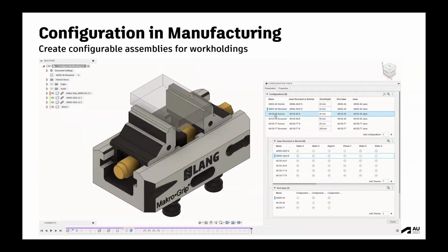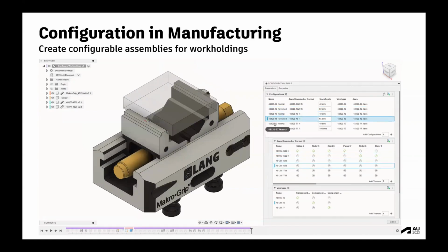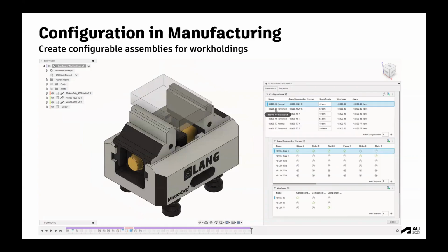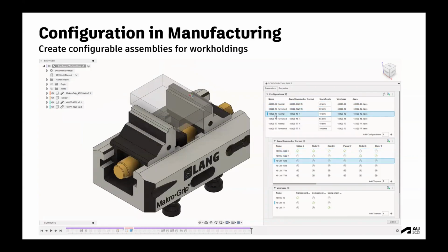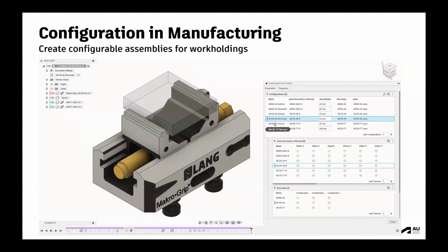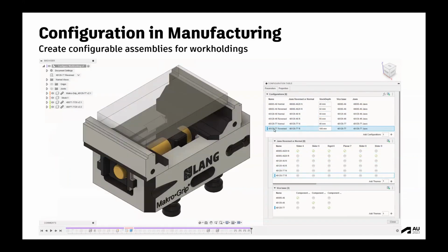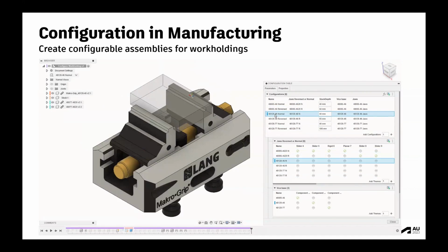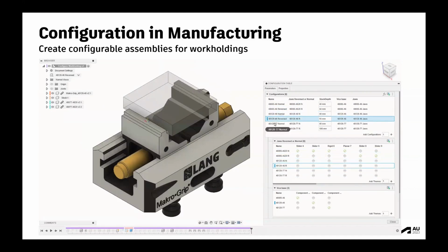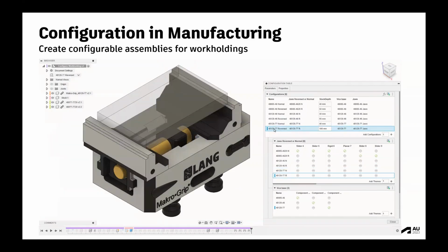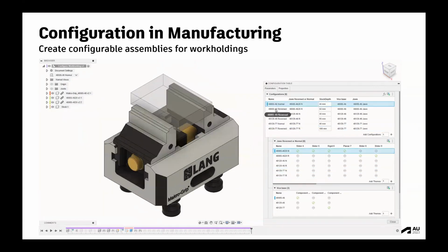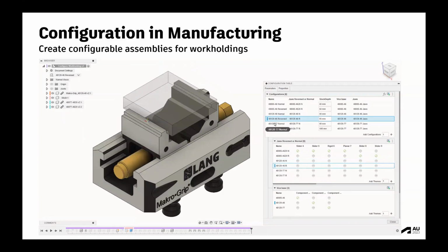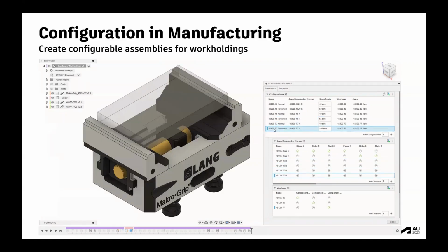With this, you are quickly making the setup by using the configuration, and not every time placing the component, placing the vices and everything. Because in reality, there are only 4 to 5 sets of vices or 4 to 5 sets of fixtures that you have in a medium-sized shop floor that you reuse every time. So why not make it standard and remove the programming or software time of placing those components each and every time? This way, with the use of configurations, you can also automate the setup.